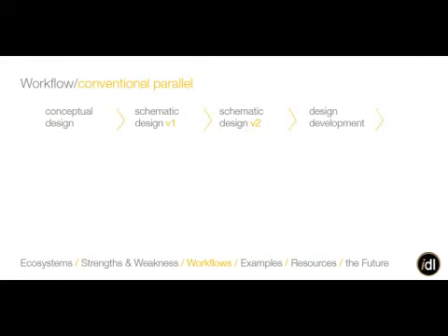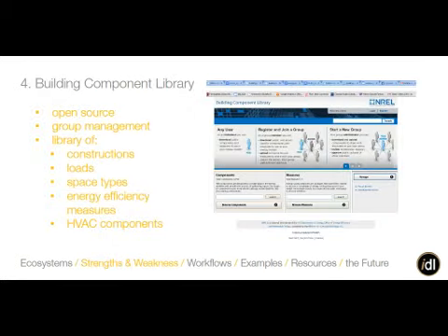Question for you. Sure. If you say you're going to model a building and you're more focused on HVAC, do you have to do a full lighting model in it to get all the watts per square foot, or is it just like entering 1.2 watts per square foot? Generally, you can keep everything at the defaults, and it'll do it based on a code cycle, so you don't have to get in there. But it does need to specify that to do all the heating and cooling balance load calculations from those internal loads with the HVAC modeling. Because you don't have to lay out the lighting in your model. You don't. No, it's just a lighting power density that you put in. Okay. But you can get into that. You can actually do it fixture by fixture if you wanted to, but we've never done it like that. We've always just done lighting power densities.